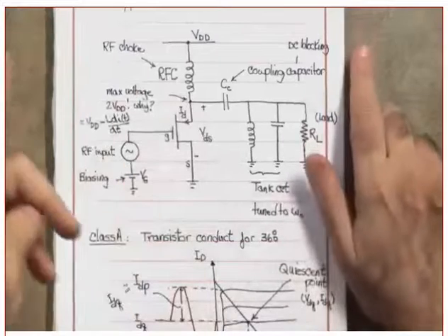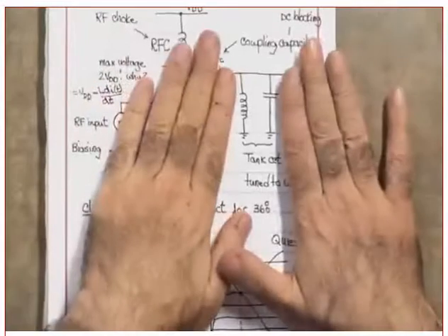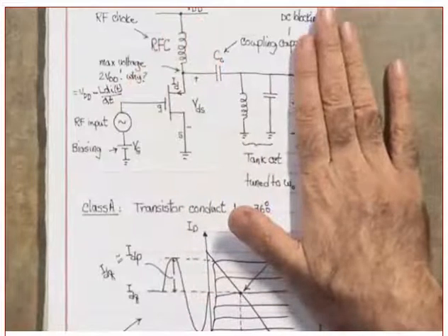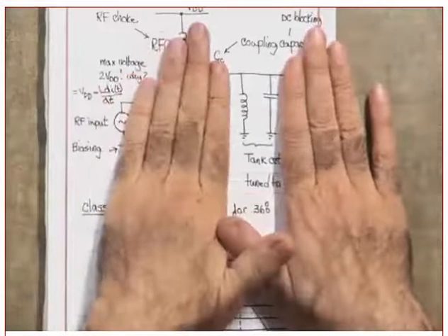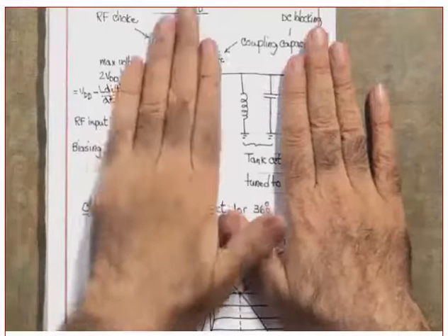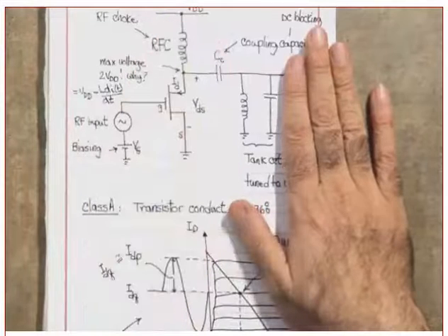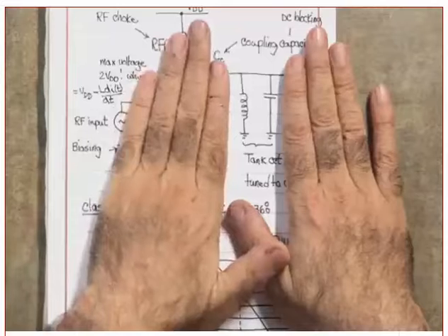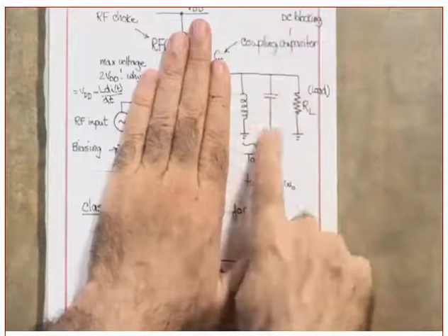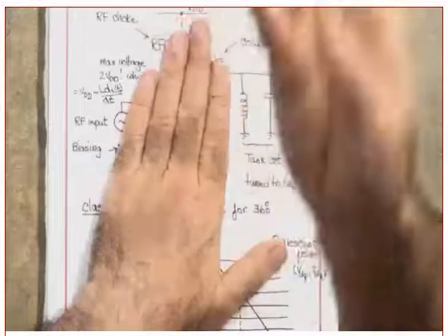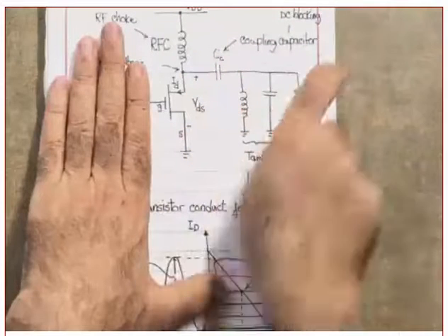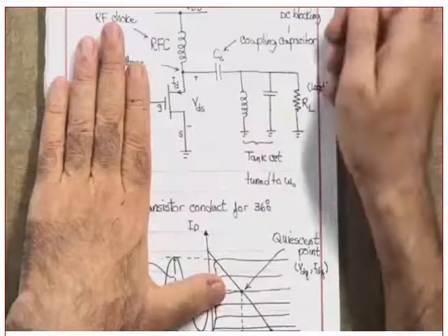Okay, let's see if you can answer the next question. What about the other harmonics? What do I want this to behave as? The other harmonics, second harmonic, third harmonic, fourth harmonic. What do I want this circuit to offer? High impedance or low impedance? See, I told you you lost me here. I want very low impedance, which means what? I want this one to behave almost as a short circuit, so that all the harmonics will come here, rather than going to the load. Yes or no?